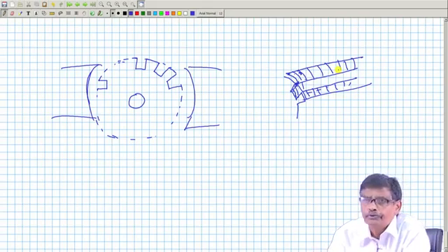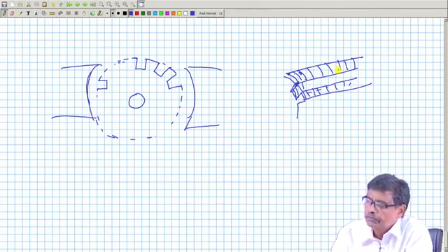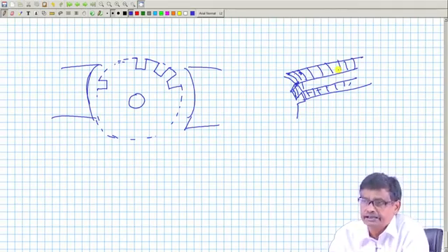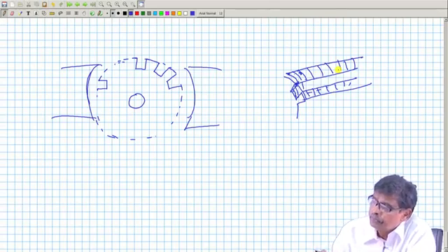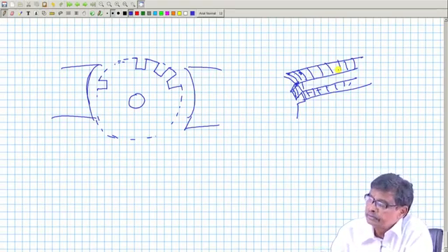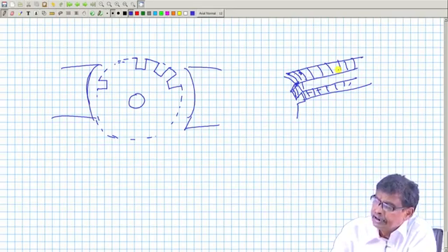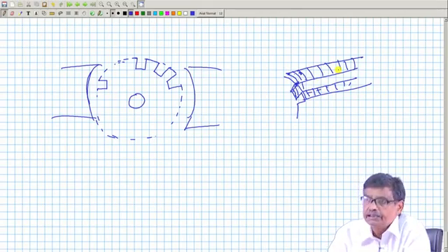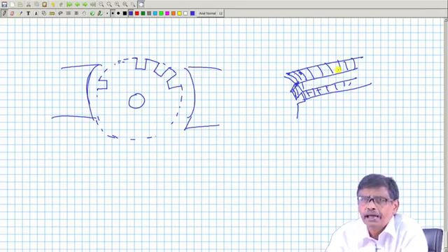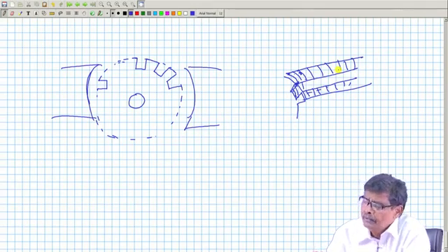So, it will be proportional to frequency square, and proportional to Bmax square. Those things are still valid here, because after all we are seeing only the AC voltage part. Therefore, eddy current loss directly depends upon the flux per pole, because from that I can calculate B. If I do Fourier analysis, I can calculate Bmax and so on.